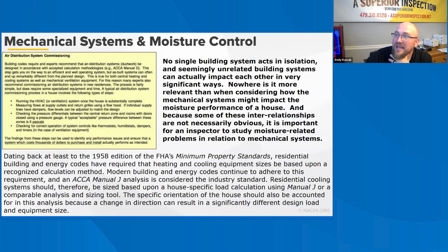Whole house mechanical ventilation is good. Whole house mechanical ventilation systems are recommended to provide fresh air and help control a range of indoor air contaminants. Systems should be designed based on the ASHRAE standard 62.2, Ventilation and Acceptable Indoor Air Quality in Low-Rise Residential Buildings. The benefits of having a whole house ventilation fan installed can be conveyed to the homeowner client.